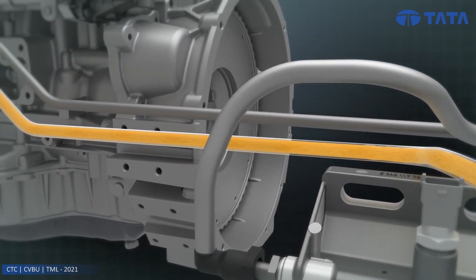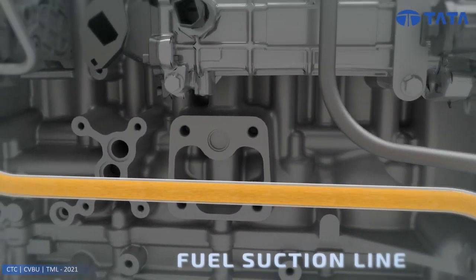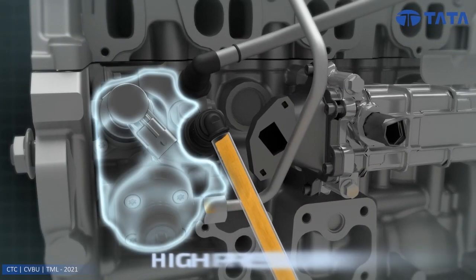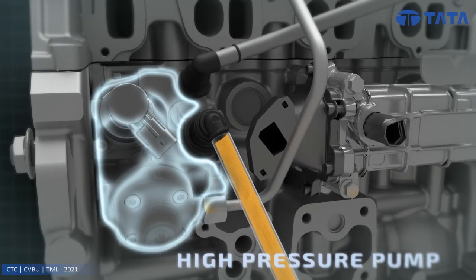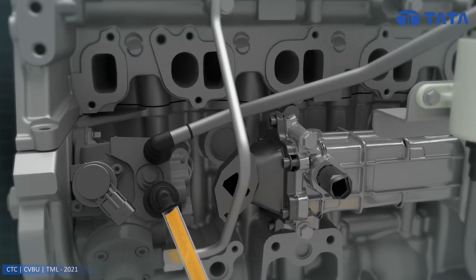The filtered fuel is supplied to the high-pressure pump inlet through the suction line. The high-pressure pump supplies the required amount of fuel to the common rail through the HP pipe, as per the demand of the ECU.